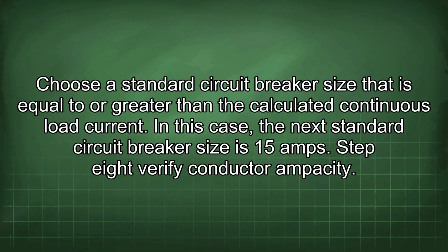Step 7. Select the appropriate circuit breaker size. Choose a standard circuit breaker size that is equal to or greater than the calculated continuous load current. In this case, the next standard circuit breaker size is 15 amps.